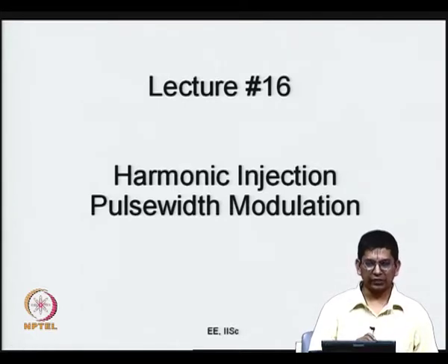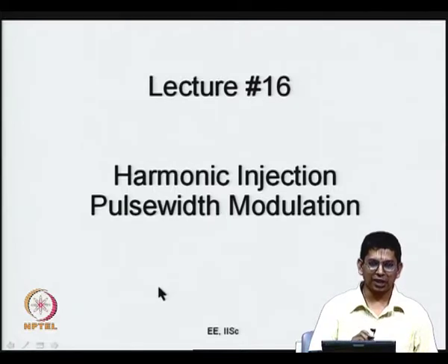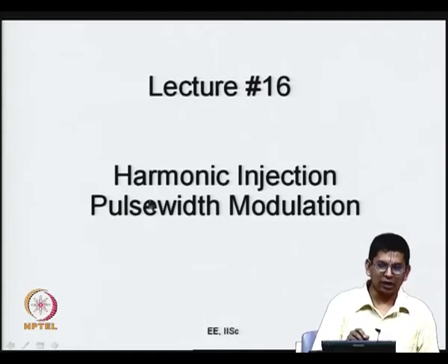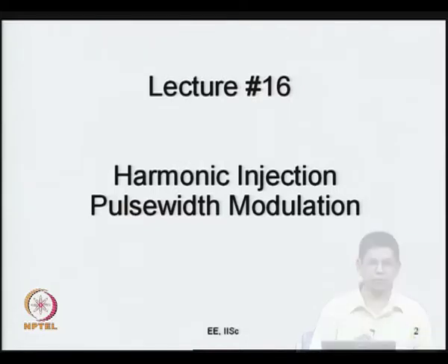So, it is a little interesting. I have often been asked this question: Professor, you eliminated harmonics earlier in the selective harmonic elimination classes, but now when you come to harmonic injection you seem to be injecting harmonics. Well, to put it jocularly, I would call these friendly harmonics. That is, these harmonics are harmonics, but they really do not matter. They will not affect the performance of your motor drive.